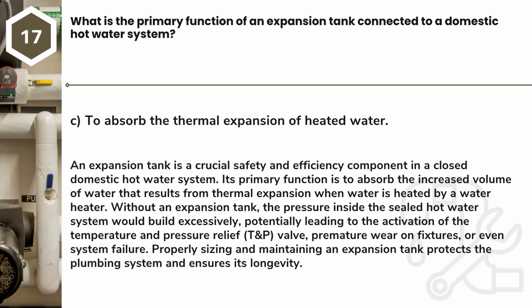by a water heater. Without an expansion tank, the pressure inside the sealed hot water system would build excessively, potentially leading to the activation of the temperature and pressure relief (TNP) valve, premature wear on fixtures, or even system failure. Properly sizing and maintaining an expansion tank protects the plumbing system and ensures its longevity.